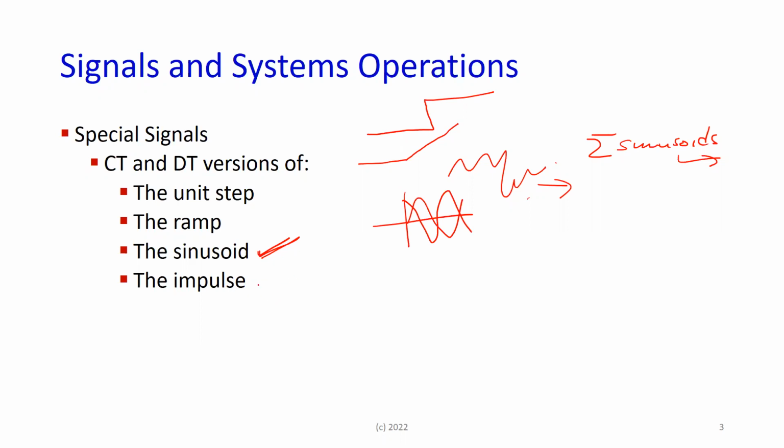And then, of course, this character called the impulse. The impulse was a funny signal in that it occupied 0 time, t equal to 0, but the magnitude of it was infinity. So that was undefined, but we defined it as an integral where the area of the impulse was 1. Right, so the power, the weight, or the energy behind it was 1, and those were the main signals, and we based our entire conversation on that.